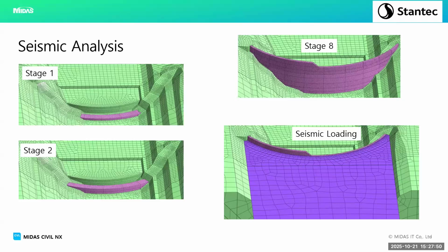If you put the dam on all at once, or even in two larger intervals, you actually get an arching stress under gravity load, which is incorrect, and then the rest of your analysis is incorrect. It is definitely key for arch dams. You can see there stages 1 to 8 are once the dam's built up, then we have hydrostatic loading or your design loading, and following that is the seismic loading.